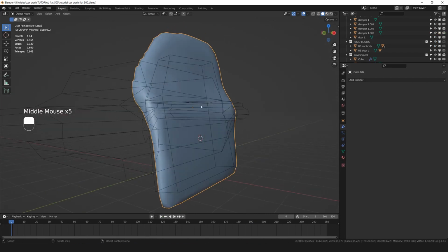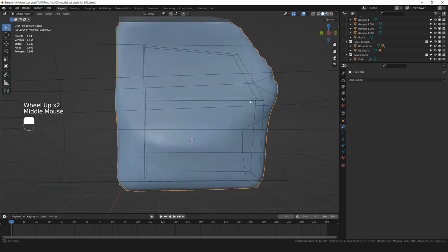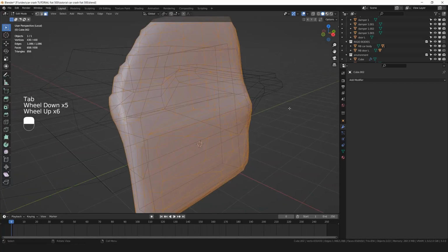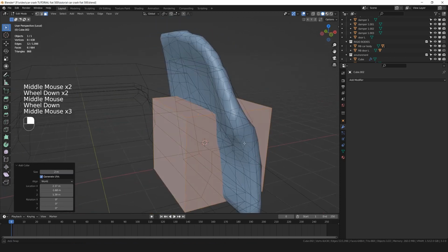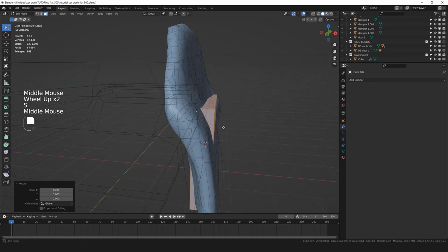Alright, and now we need to create the internal vertex group for the pin group, which is a little bit tricky because this door is kinda almost flat. So, enter edit mode. I'm gonna click outside in order to deselect, and then Shift A, add in a cube. Pay attention that we have added this cube while we were in edit mode, not in object mode. We are just adding vertices, so just work on this cube until it stays inside the door.